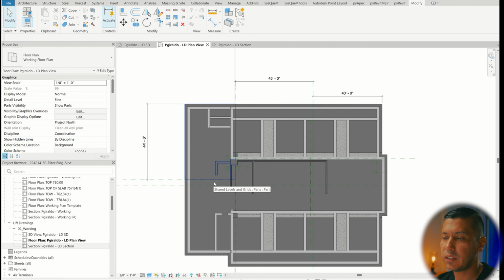All right, so now that we did the slab pours, I'm going to go around and do the exact same thing and break up all the different walls into the different wall pours. So exactly the same thing. I'm not going to show you guys step by step how to do it, but essentially just use the reference planes and then label them correctly, same as the wall pour numbers that you're going to use. And then go to parts, divided parts, and then just break them up into all the different parts.